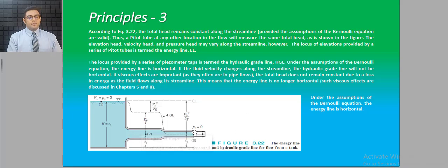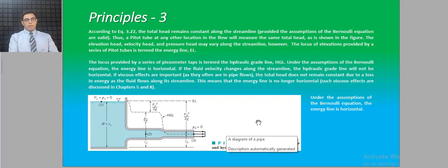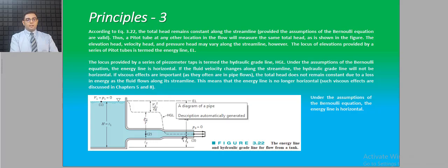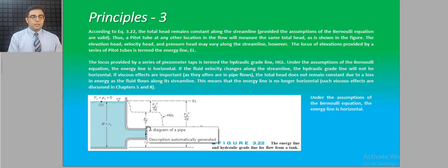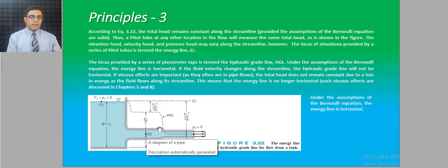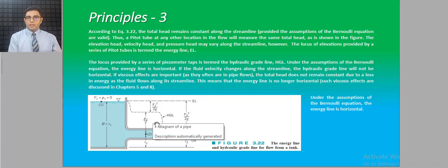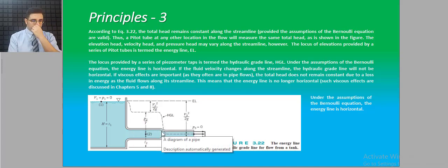There is a concept in this figure as well. There's an energy line above. As we come down, the amount of the energy line is going to be decreased by v to the power 2 over 2g corresponding to the point. If we are under the HGL for calculating the pressure head, the pressure head at this side is positive because we are under the HGL.